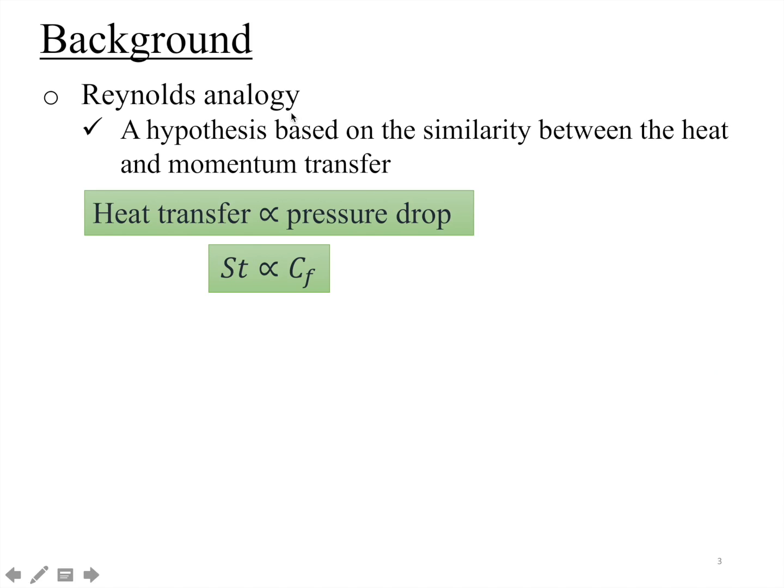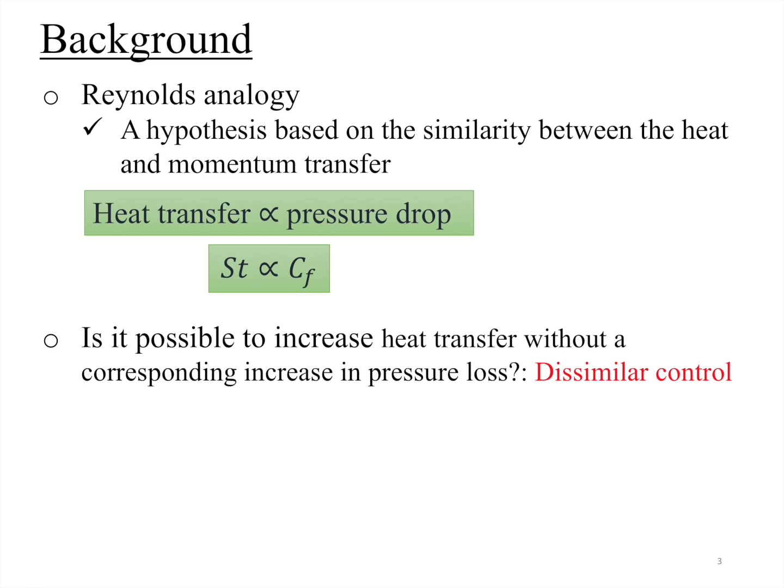But according to Reynolds analogy, a hypothesis based on similarity between heat and momentum transfer, any technique that aims at improving the heat transfer will also result in an increase in the pressure loss. Since Reynolds analogy is not based on any physical law, the natural question that we can ask is, is it possible to increase heat transfer without having a corresponding increase in pressure loss?